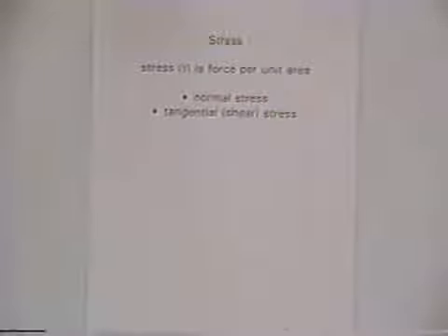Now we'll deal with stresses, forces per unit area, and typically you think in terms of normal stress and shear stress. When we get into fluid statics in just a second, though, in statics, the stresses are just normal because there can't be shear stress, or the fluid would be moving by definition, and it would be dynamics.